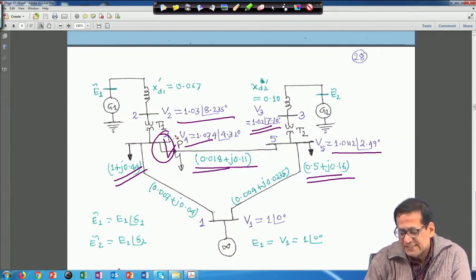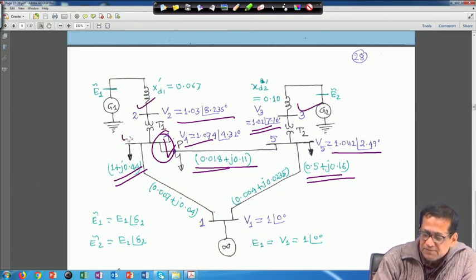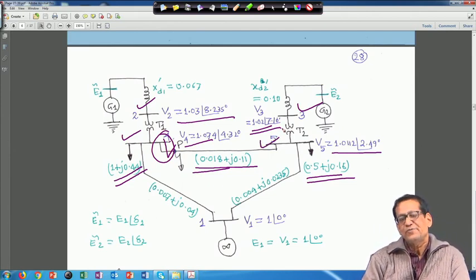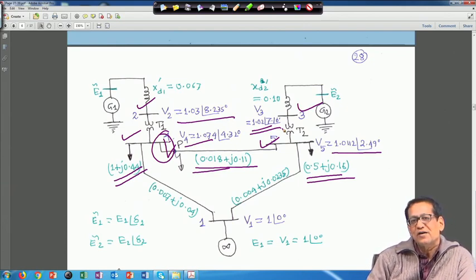So, first thing is, this is bus 1, bus 2, bus 3, bus 4, and this is bus 5. First you have to make the 5 by 5 Y matrix, right? And when the fault has occurred at bus 4, the voltage at bus 4 during fault will be 0, that means the 4th row and 4th column of the Y matrix will be eliminated, right.